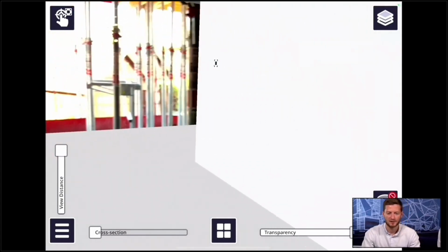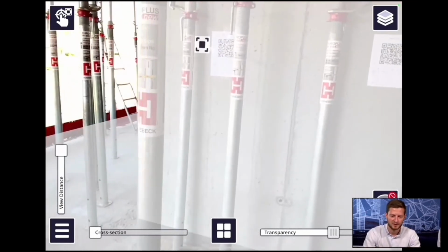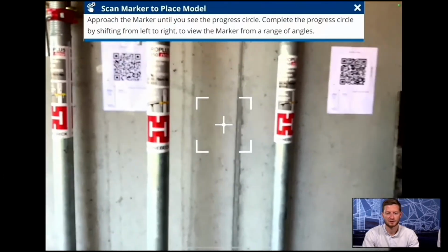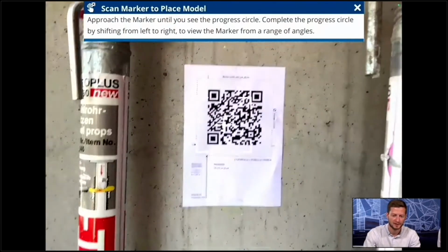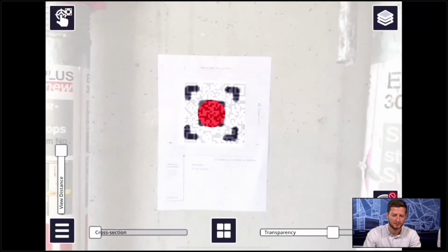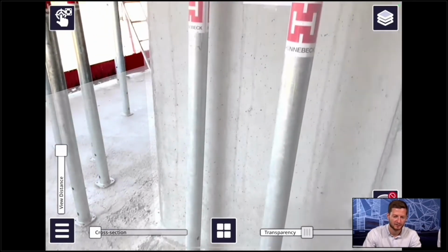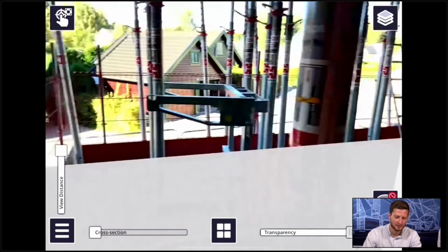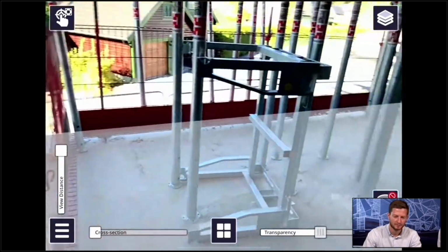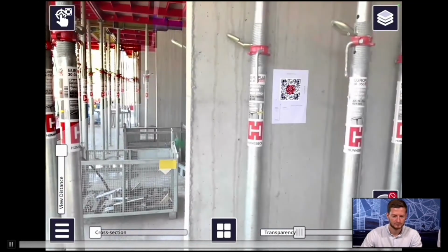And as mentioned, as we move forward from the QR code and we are shaking the device, it might drift a little bit. So then we should go to another QR marker, tap on the left top corner of the screen, and add another QR marker. And the model is aligned again. So we can see that on the other side of the building, it's again pretty accurate.